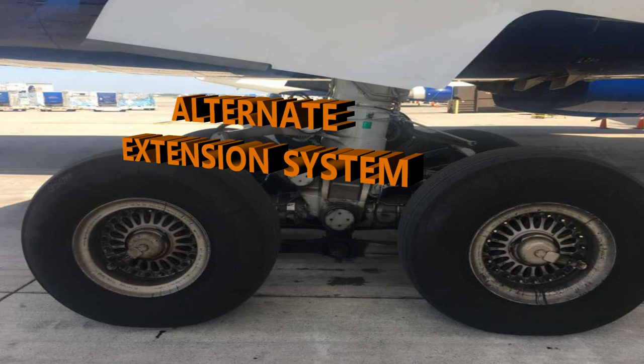It's an alternate extension control module that would need to be pushed or moved downward. That third position is the down position, so that's the down command, and that starts the triggering of the alternate extension system. Now, what is involved with this alternate extension system?